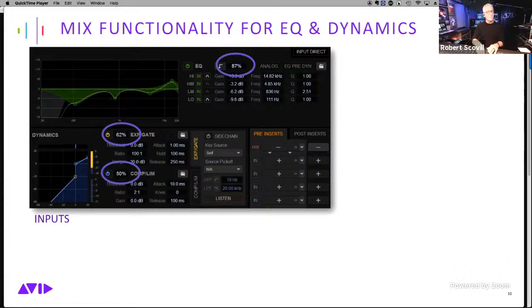Same thing applies for a gate. And we don't talk about this kind of thing very often in live sound circles because it's been very difficult to do. But in the studio, it is not an uncommon thing to do parallel gating, where, let's say, for instance, you might have a drum, which I'm going to actually try to demonstrate for you today, which is a little mushy or a little soft sounding, and you want to give it some impulse, some impact. So you actually take a noise gate and put a very chippy gate on it, something that's very quick, very transient, and just add that in with the natural, original sound, and you get something that's a little more transient on that drum and still sounds very natural, right?